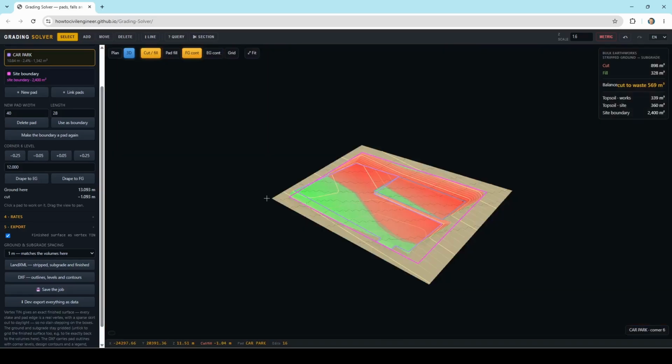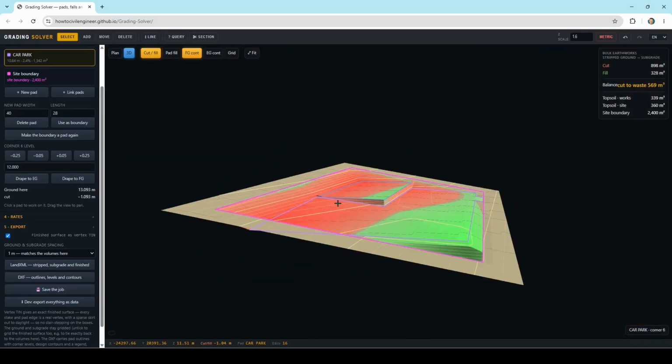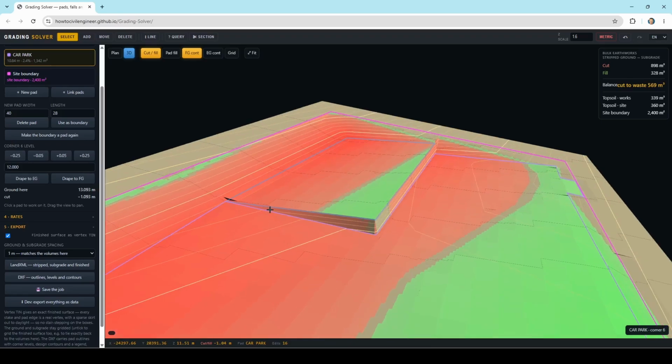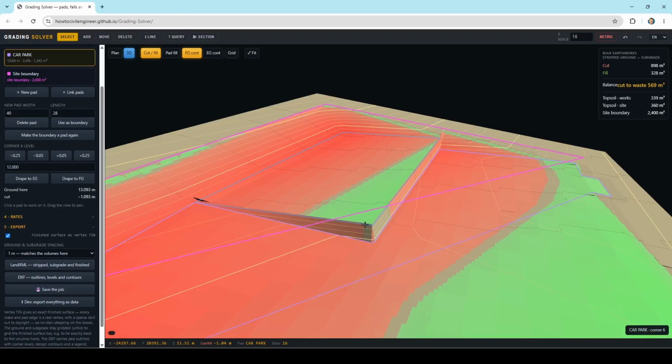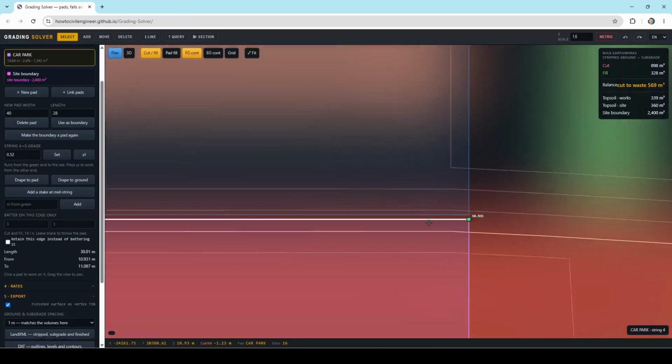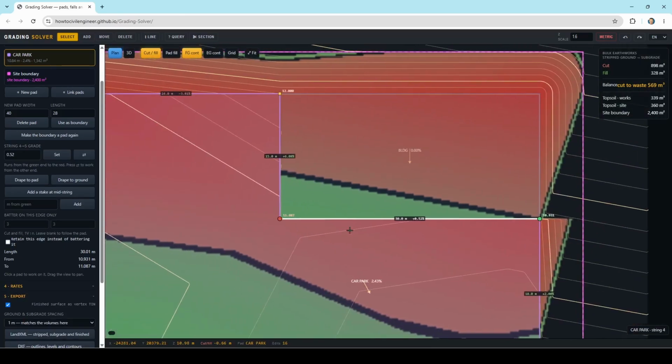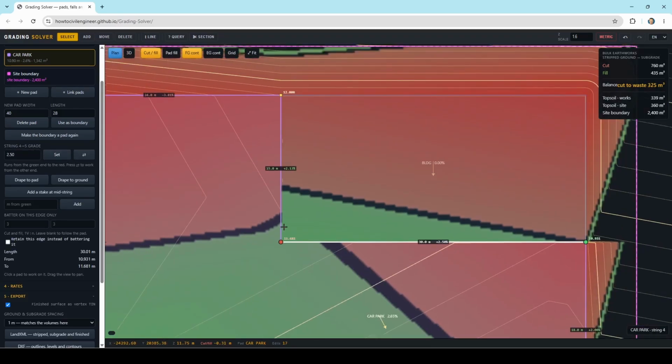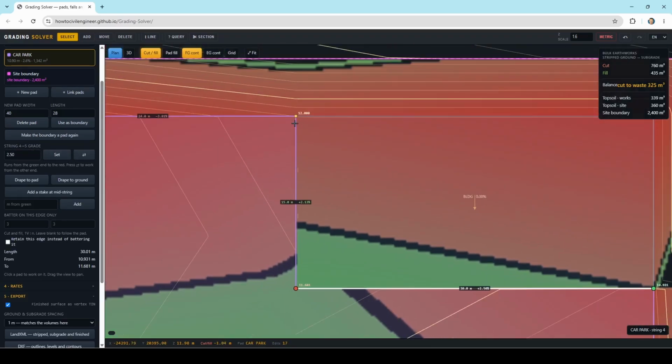If we look at that in 3D, just out of interest, you can see that's going to be difficult to enter. So what you could do is create another break line there, and then have that as 12 and make that steep coming up. But we can make this one a little bit steeper, and then this will get rid of how steep it is along the side. So there's this line I want here. Okay, good. Set this one to 2.5%. Now that's a reasonable 2%, and that's easy enough to work out minor grading in this area to solve that one. Pretty happy with that.